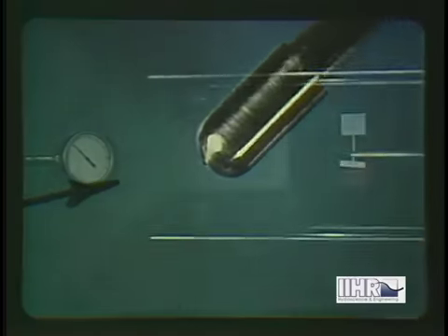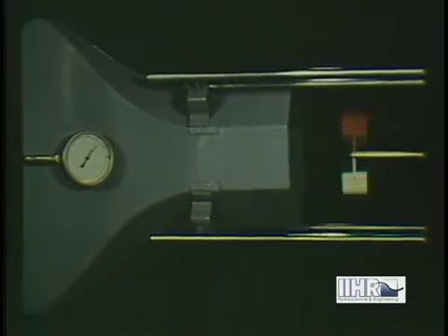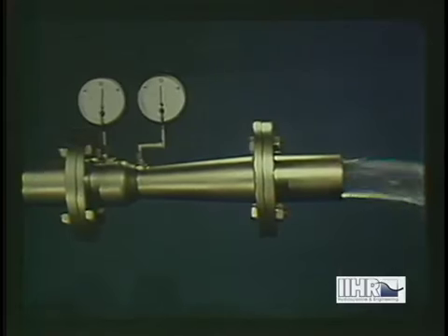Instead of the acceleration of flow around a body, the acceleration of flow through a conduit transition, for example, the contraction preceding the test section of an air or water tunnel, can be used in the same manner to produce a pressure change that varies in a known way with a velocity change. A similar condition forms the basis of what is known as a Venturi meter.